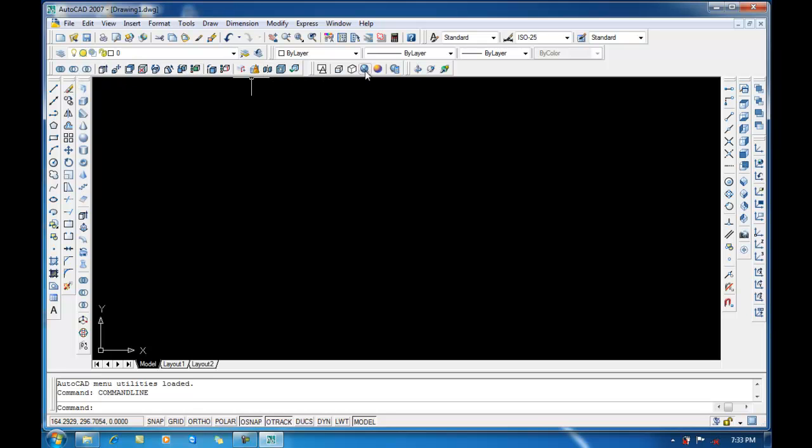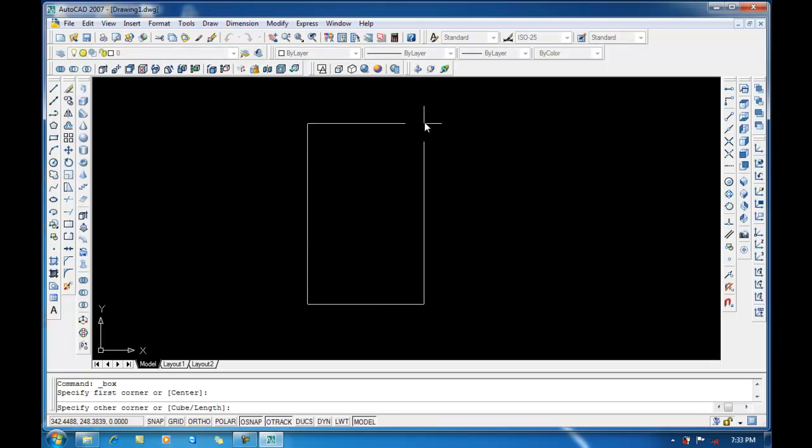As you know, this is the visual styles and the orbit. Okay, let us directly go ahead with one box where we can edit that solid as per the customer requirement. See, now we have clicked on the XY plane, it is asking the Z. I can enter the value or I can click also. Go for the 100. We are not seeing the third axis because we are working with the X and Y plane. Okay, this is the top view.